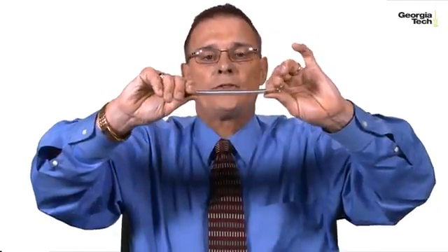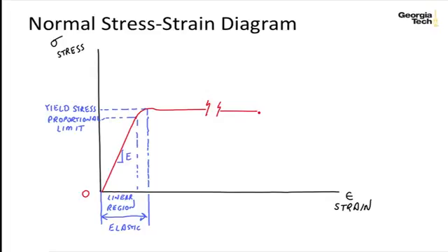And in fact, if I go back to my spring here, once I get beyond the yield stress and I continue to get strain with very little additional force, you can see that I just start to plastic out. And so it just becomes perfectly plastic. And so let's draw that. So this is the perfectly plastic yielding.